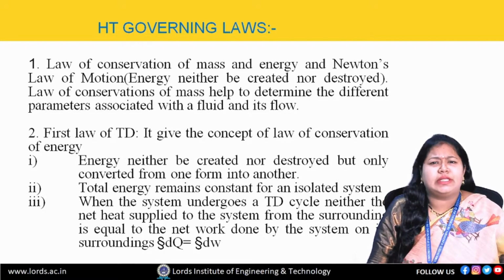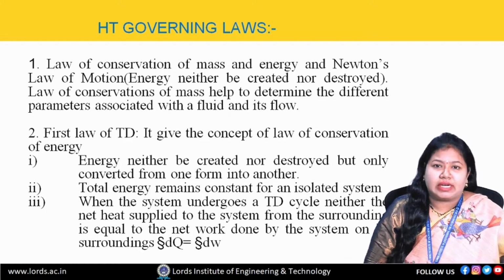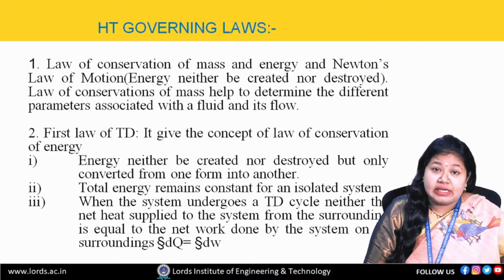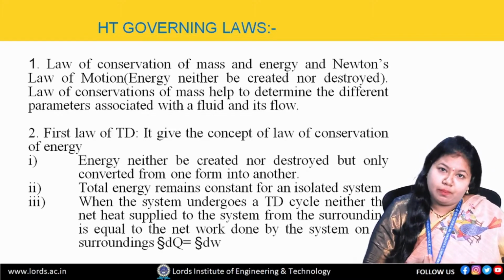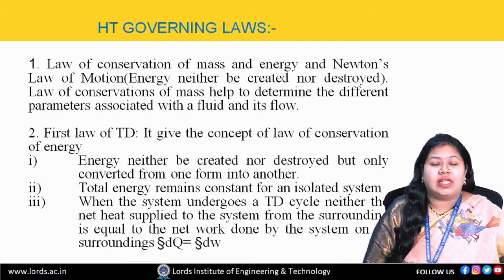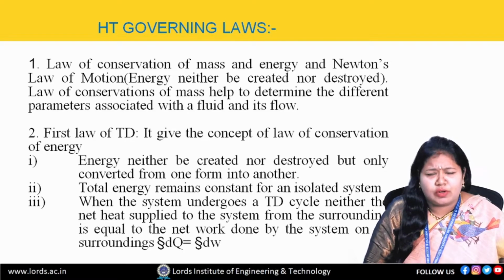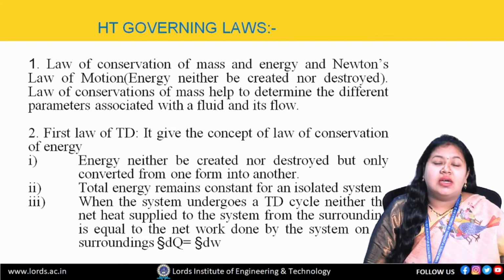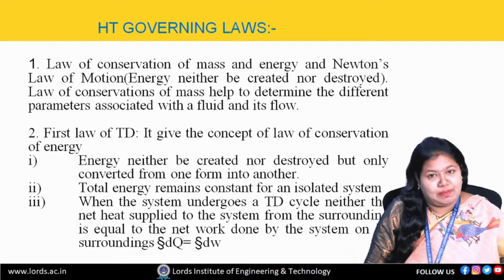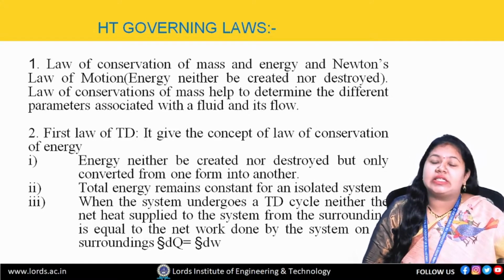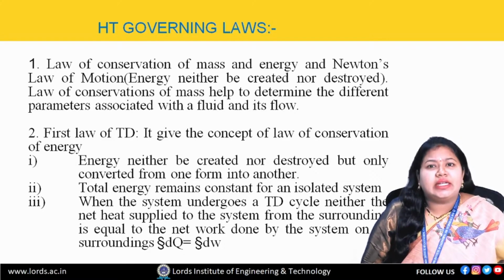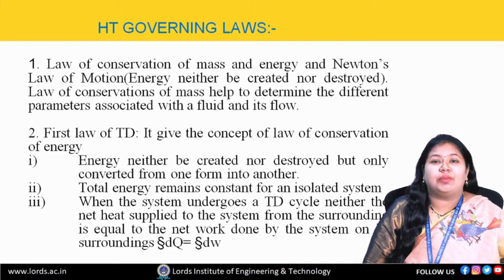A very simple example: we consume food. Let us think 2000 calories of food we are consuming per day, 1500 calories is the work done by a human being, and 500 kilocalories is stored, obviously, as fat inside the body. This is the best example for the first law of thermodynamics. The summation of internal energy and the work done is nothing but the heat supplied. dQ is equal to dU plus dW. The cyclic integral indicates that this is a thermodynamic cycle.